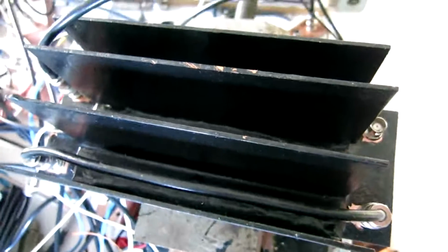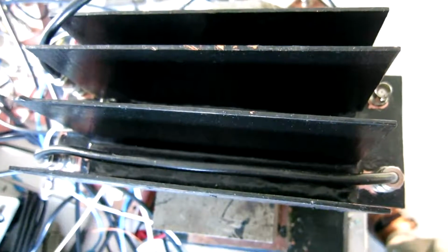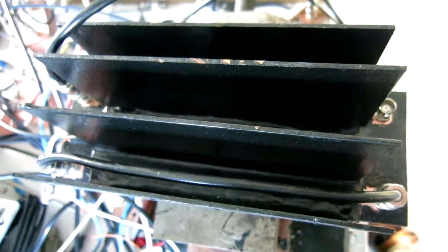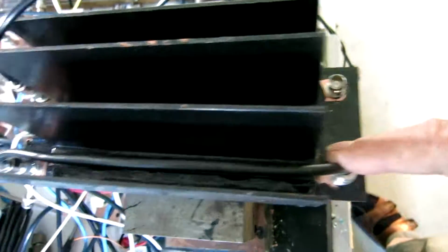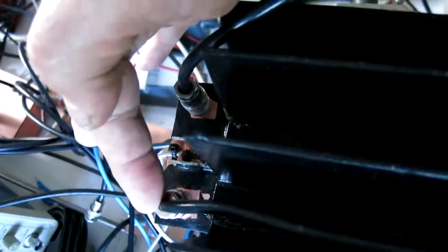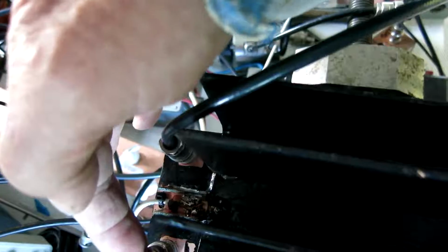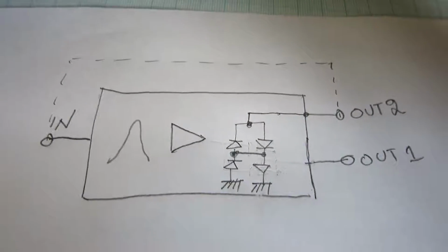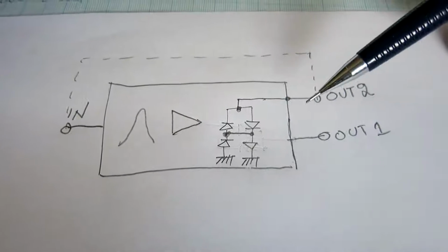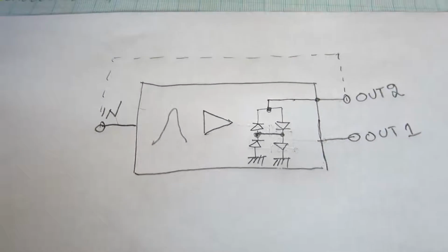In this video I will show how I try to understand the origin of sideband noise in this selective amplifier. At the moment it is running as an oscillator. Here is the input and here is an output which is amplitude limited by crossed diodes, 1N4148 in series, two such units. So here is the block diagram, and a connection from this output, the limited one, to the input brings the unit to an oscillator.